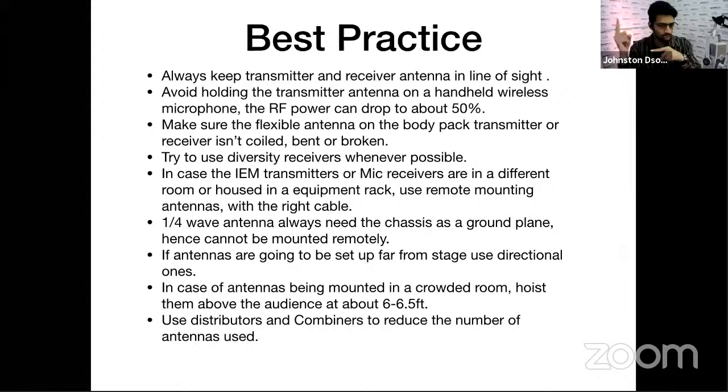The reason why you cannot remotely mount them is because they always require the base of the chassis to give them the amplification. Okay, because that is going to reflect, so it is going to increase the power of the signal that is coming to the antenna. If you disconnect that, then it might not work as well. That's the reason why it is designed to be made small, so it can be mounted on the chassis, and the chassis is a part of that antenna. Do not disconnect that and think, okay, a small antenna which is about 4 inches in height, you can go and mount remotely. You won't be able to, because the RF output of that antenna won't be strong enough to travel through the cable and reach the chassis. So it is meant to be mounted on the chassis itself.